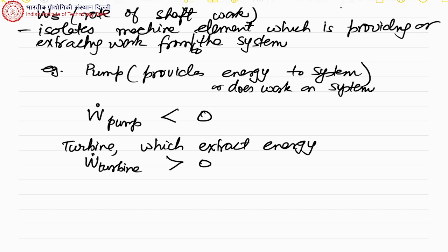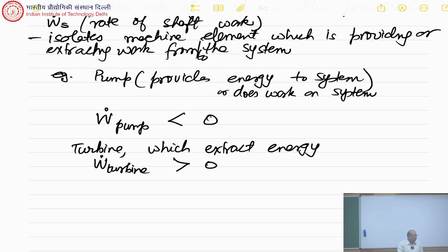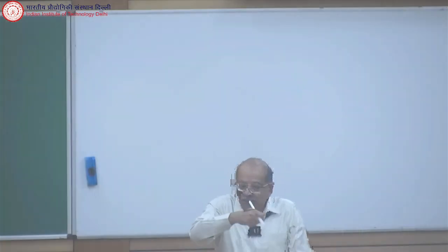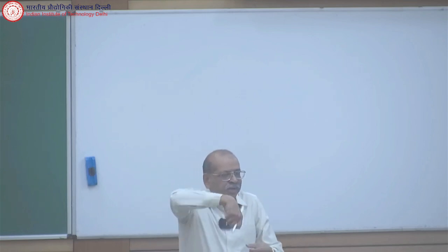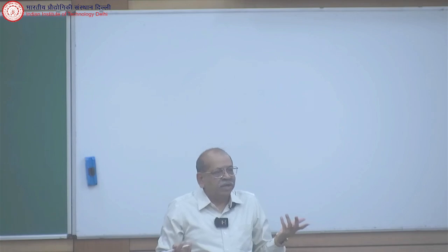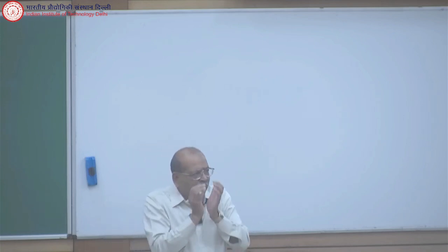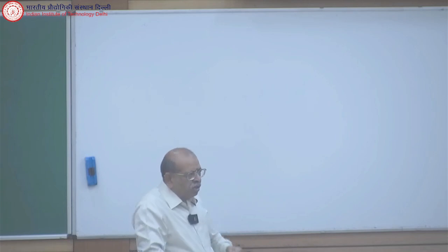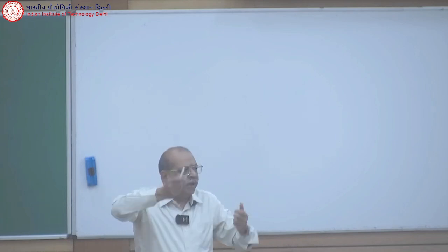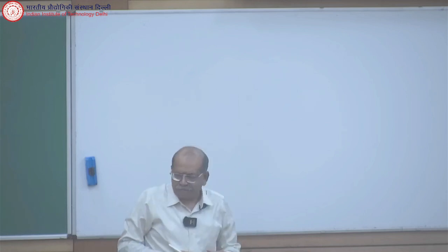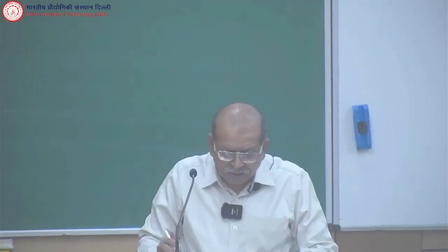And actually, sometimes we will assume the fluid is inviscid. But even if we assume inviscid, for an inviscid flow there cannot be any shaft work, strictly speaking, because the work is done only through viscosity. Whatever energy comes to the fluid is only because there is some viscous effect, otherwise the body will just keep on rotating without any restriction. So, that is in some sense an engineering way of clubbing all the work extraction through the external surroundings in W dot S.